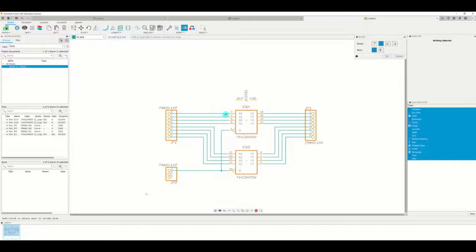Okay, so what I do is, for short lines, I just connect the lines, but for longer lines, meaning let's say one component is here and the other component is far away and you have to pass through a lot of other wires, it's better that you just draw a short net connecting the pins, and then label that pin, and then on the other side you just draw a short line and then label the pin, and the two will be connected. We can do that later.